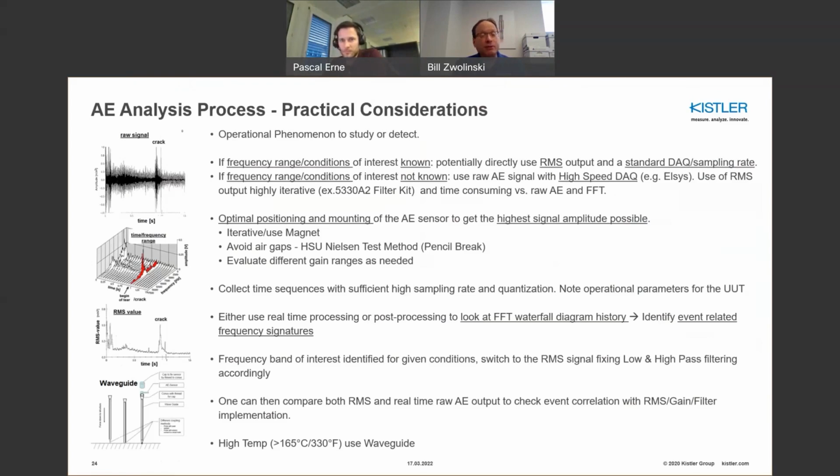So you need to really investigate that and look at what magnitudes of AE signals, where you are mounting the sensor, and what frequencies these AE events are at, so you can better create detection criteria to support your condition monitoring solution. So again, that's very important.